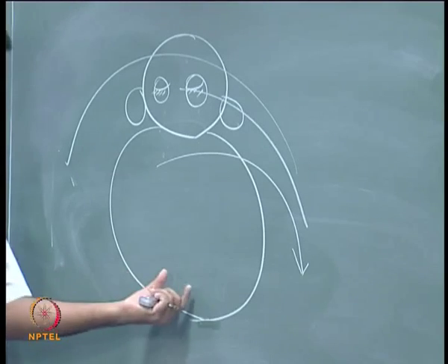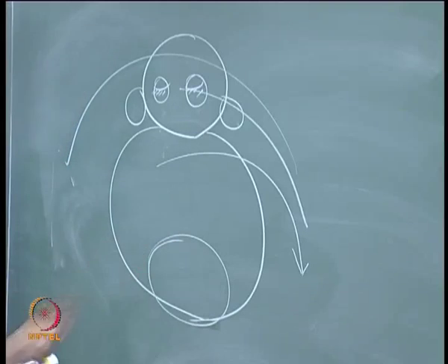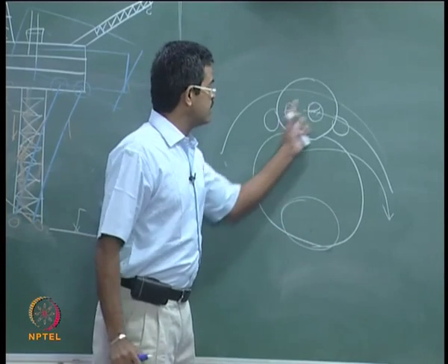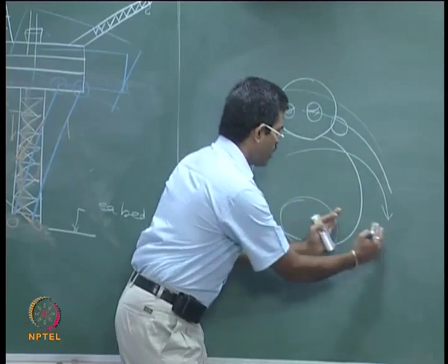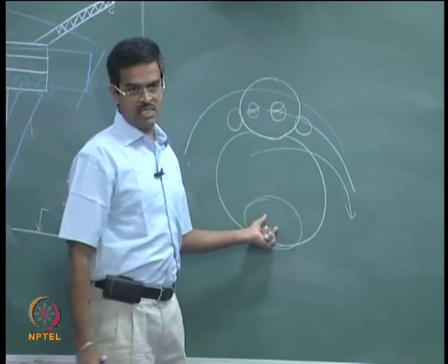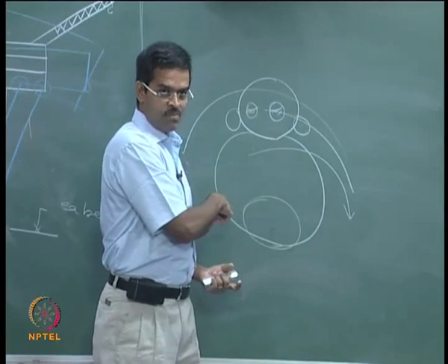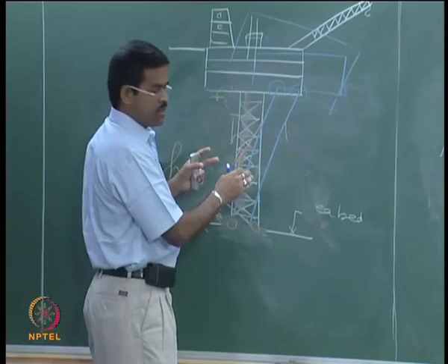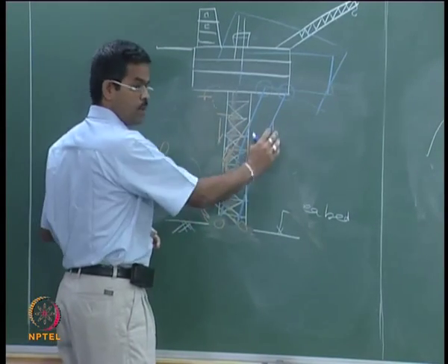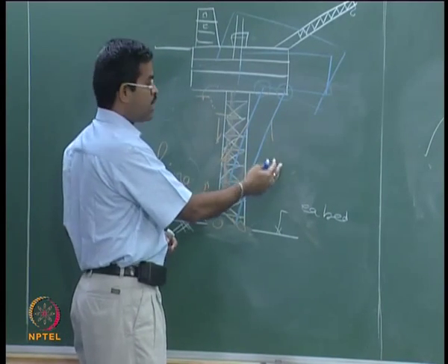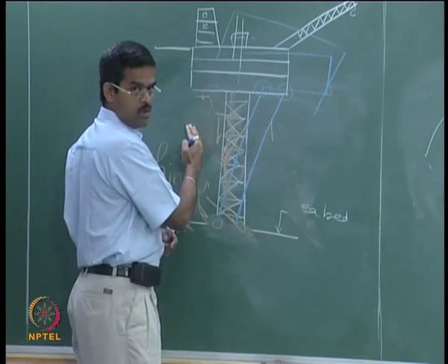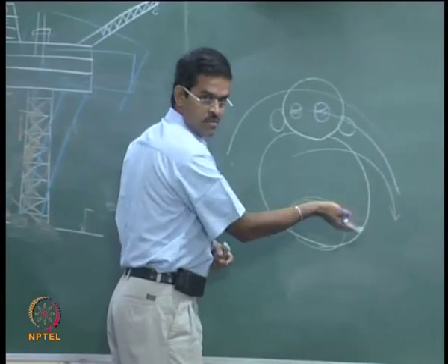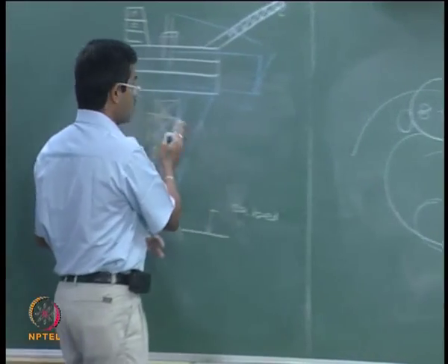It is exactly the same model applied here, which is a spring mass system, which integrates this weight and the shift of buoyancy or shift of weight to the spring action restores this position back. So, I have to have a mechanism in such a way that I do not have an additional member like a mooring line, but I want to bring this tower back to normalcy without oscillation, but here the toy oscillates. Okay? I do not want that oscillation to happen.